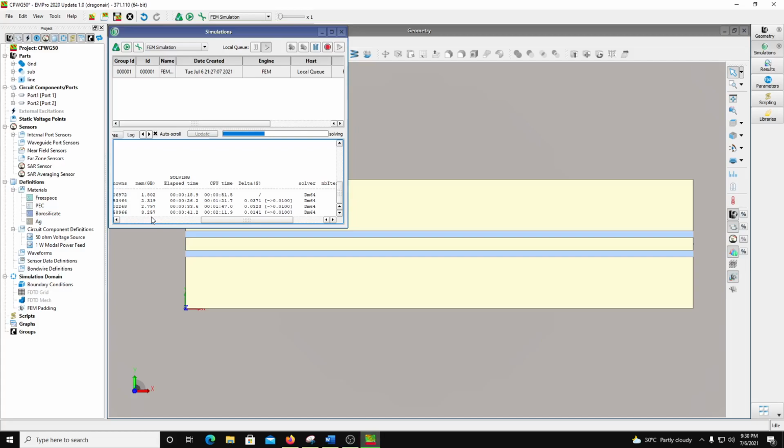Hopefully this one will push it below 0.01. It depends on the luck, I don't know. Actually, meshing depends on the seeding. Okay, so the seeding is your initial mesh, so you can control that also.